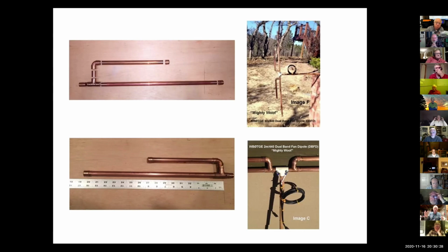If you ever are trimming an antenna length down to what you're trying to get to, and you end up cutting it too short, well, no big problem. You just whack off a chunk of copper pipe, put a coupler in, put an extended piece out, and you're looking good. So with these kinds of antennas made out of copper pipe, you can make just about any kind of antenna that you want. Dipoles, verticals, almost any frequency can be made out of this kind of material.